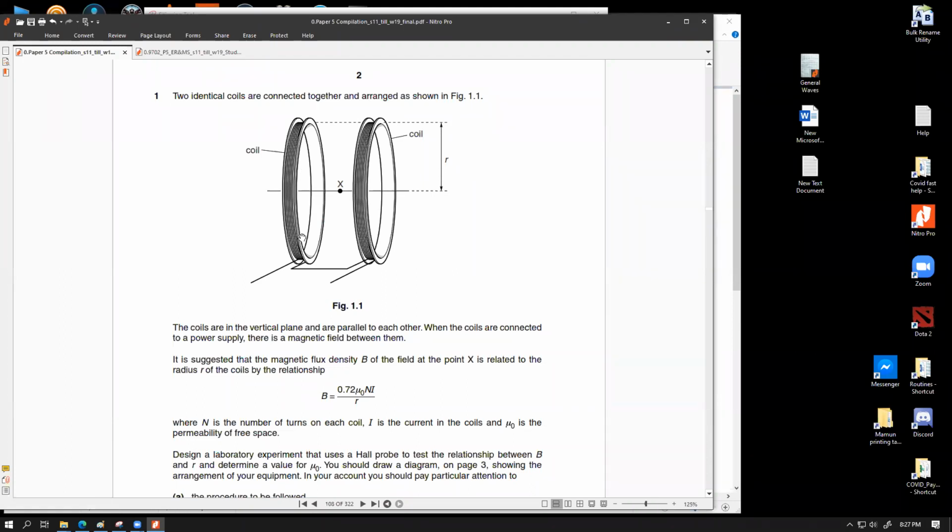Or you can make a spacer, or cut up a piece of wood or styrofoam, which you can use for your measurement in different places. So you can use a reference length so that they are both equal at all the locations before you start to take your reading. And also, what is quite important is that to make sure they are vertical, we have to use a pretty long set square, or a set square that is attached with a meter rule, to measure in different parts of these circular sections.